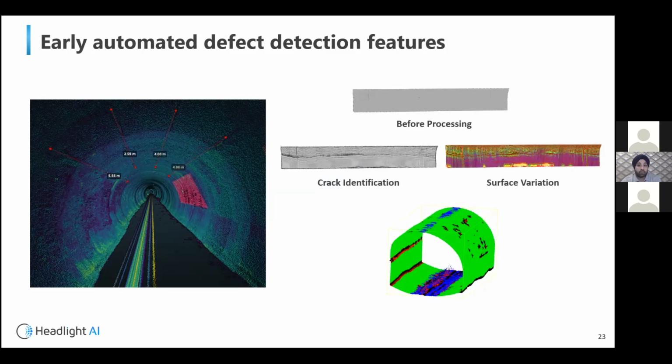On the right we show the variations in the local geometry of the point cloud, which is primarily due to several reasons, stress, and also could be the earth above pushing inwards onto the pipe or the sewer. So we've tried to identify what this variation looks like and give it some color. That's what you see with those various colors from purple to green, and where there is high variation, you have lots of noise in the color. The bottom was early experiments on understanding where we have cracks, where we have side inlets, and how we can identify water if it is semi-flooded, for example.